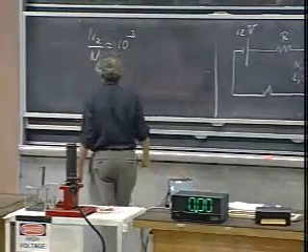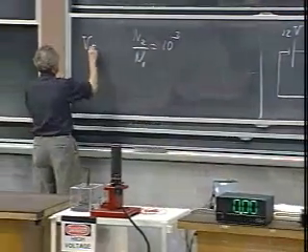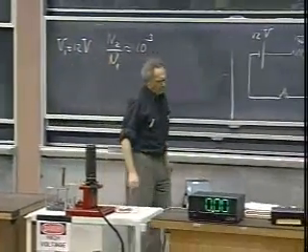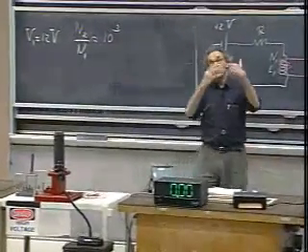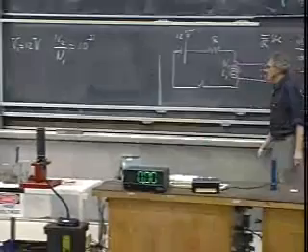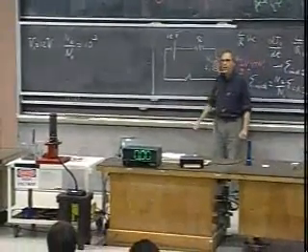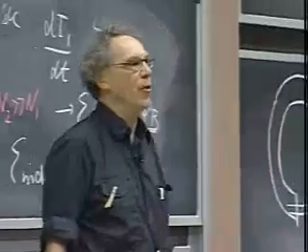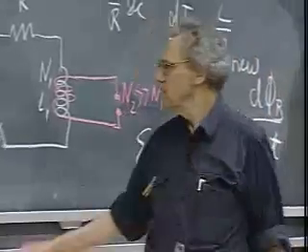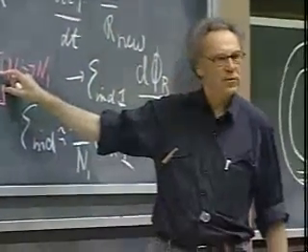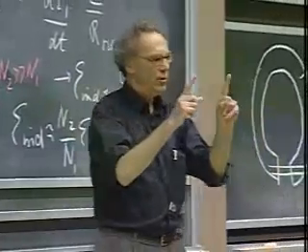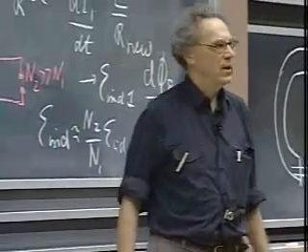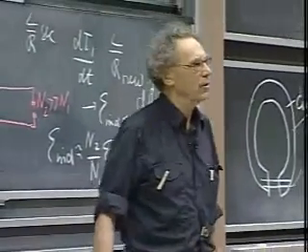And we run it with a car battery, just like your car, 12 volts. We let the current build up in the primary, just like we have here, and then in a very cruel way, we open the primary, and we create in the secondary up to 300,000, 400,000, 500,000 volts. And then you will see a spark fly over here at 300,000, 400,000, 500,000 volts. You can draw a spark over a distance of 10 centimeters easily, because all you have to do is get above 3 million volts per meter, which is the breakdown electric field.